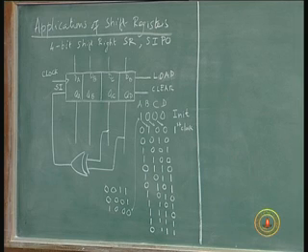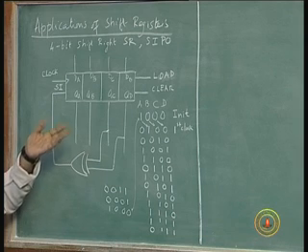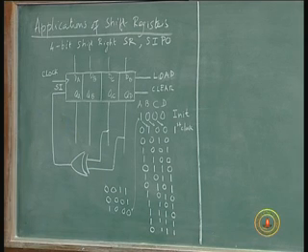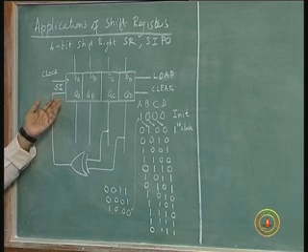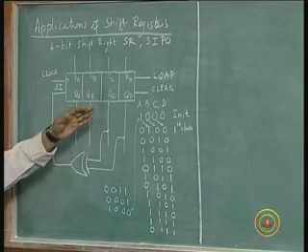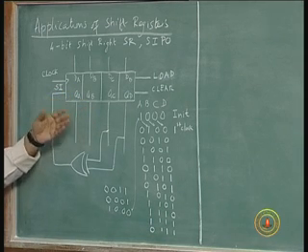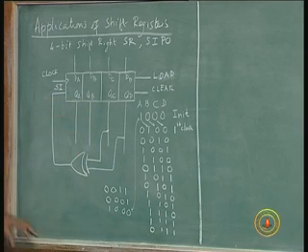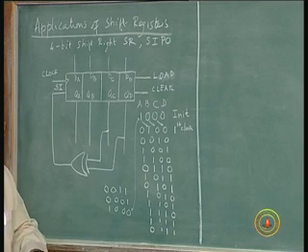So, by just putting in one initial pattern, of course this is only an arbitrary pattern, it does not have to be 1 0 0 0, you can put any other pattern too, every time you apply a clock pulse the bits get shifted one bit position to the right, and a new bit is added to the left, and then again shifted and so forth. So how many different patterns are here?